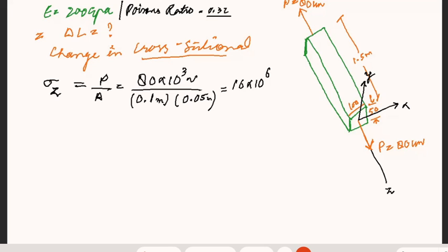So firstly, we have calculated the stresses in your z direction, how much amount of stresses will be there in z direction. And then we can also check strain in our z direction. Strain in our z direction will be simply how much? It will be stresses in z direction divided by modulus of elasticity, E_st, for steel.